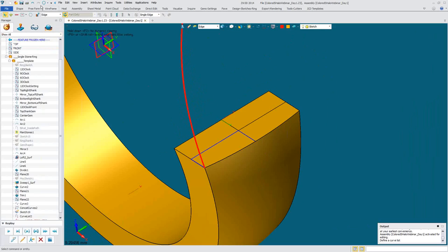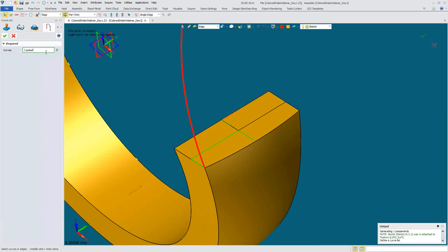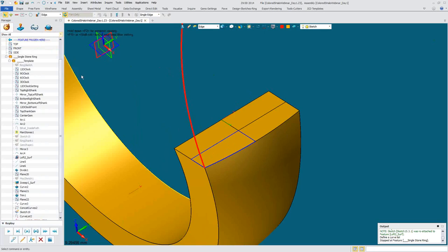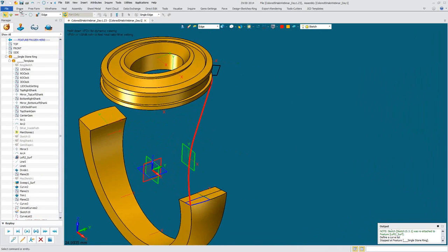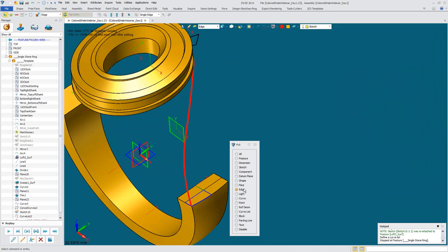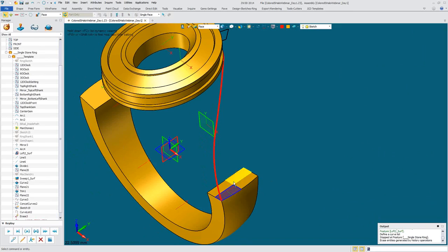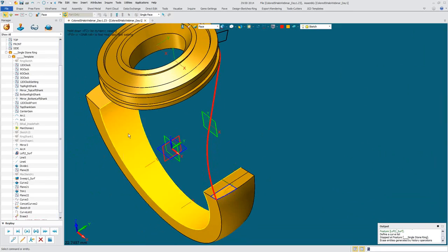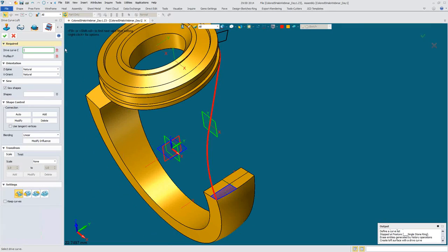It looks like I missed one. Okay, so now we'll come in with shape. We can also come in and erase this face prior to if we want, and do this with open end caps, and later on we'll sew it. Shape, drive curve loft, same thing as a standard sweep in Rhino.